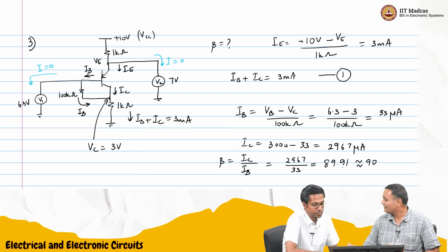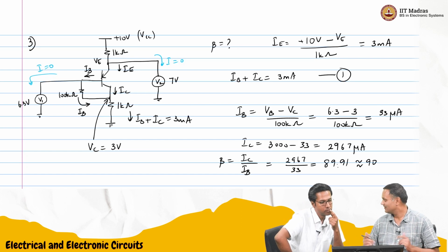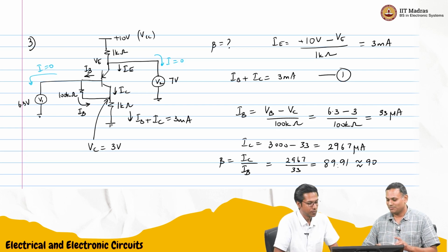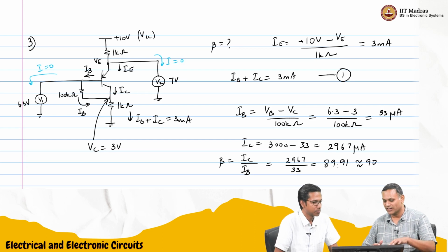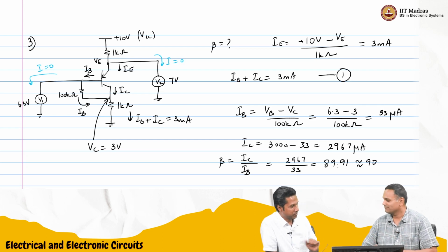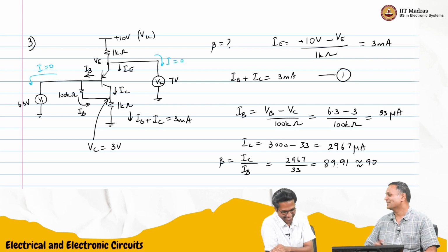You will never have this level of accuracy for beta in any measurement. So, this was a nice problem. The important thing to realize is that the question said you are measuring the voltage, not a voltage given to the circuit. That part was a little hard to understand. You also have to assume it's an ideal voltmeter, so current is 0. Everything else was easy. You use the transistor equation, then KVL and KCL, and you can solve the problem with basic algebra only. This is slightly easier than phasors with complex numbers, and much easier compared to the Laplace transform.